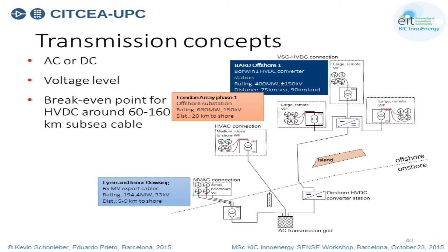And just to give you an example, nowadays HVDC connected wind farms are mainly in Germany because they build offshore wind farms very far from shore, and what they then do is have one HVDC substation, and they connect up to 3 wind farms to it in order to match the power rating, because the HVDC converter can now be like 900 megawatt, for example, and then you try to connect 3 wind farms of 300 megawatt, and then you have a small offshore grid which is in AC, operated by this HVDC converter and consisting of these 3 wind farms.